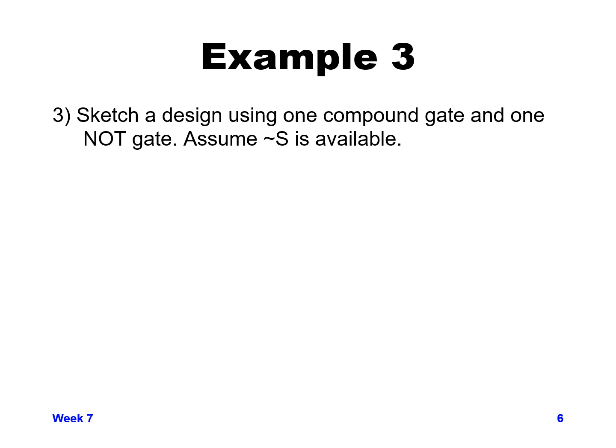If you need a little bit of a hint, some of you might have used this compound gate or something like it to do an XOR function in the past. Go ahead and sketch this, not at transistor level, but at gate level, what you would use for one compound gate followed by a NOT gate. So pause here.